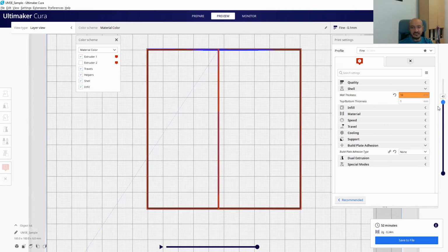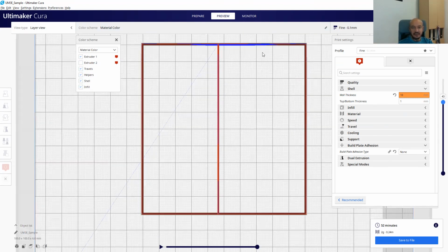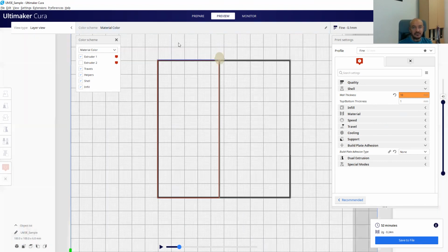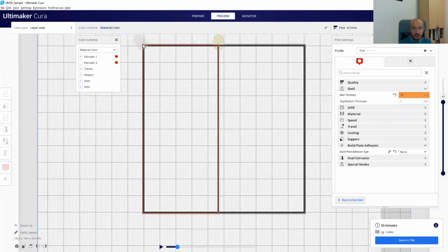Now let me focus on an intermediate layer. So what is going on here? Two edges are printed, 3, 4. Now 4 edges are printed. Then what is done? As you see, there's a fast motion between this point and the next point. Now you will see that when I click the arrows on the keyboard, there will be a blue line. Yep, you see there's a blue line. It means that during this motion, no material is deposited, the head is just moving from left to right.